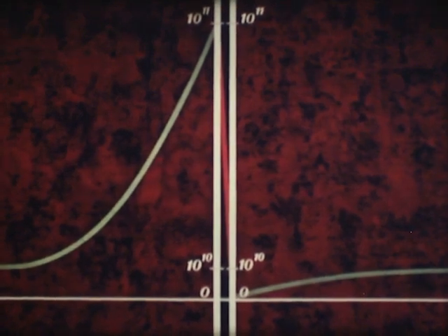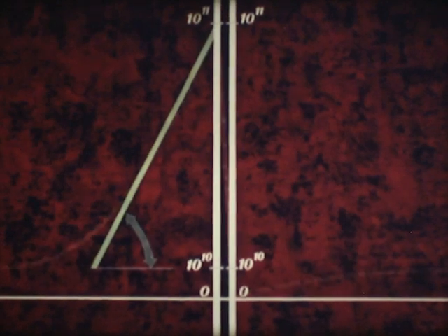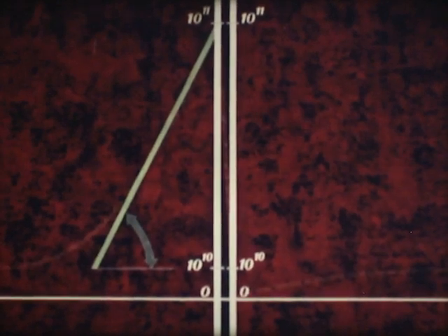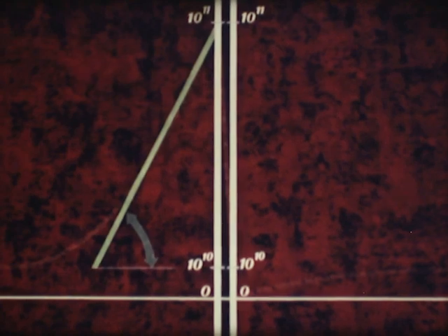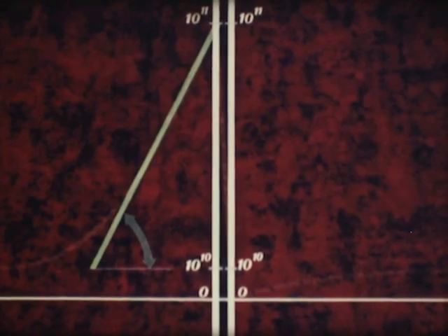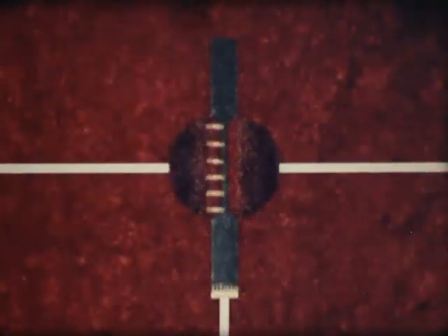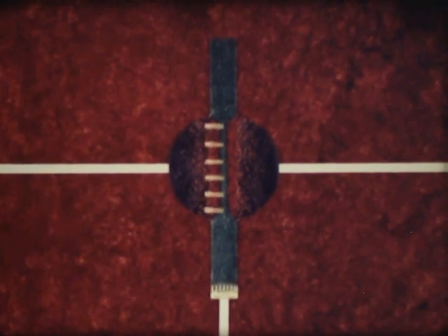The steep curve representing the appreciable deviation at the left-hand junction can be replaced by a straight line, and the angle that this line forms with the horizontal axis has a direct relationship with the number of electrons diffusing from the central region into this P region, where they recombine with the majority holes. To ensure a continuation of this electron flow, the battery has to supply electrons to the central region.